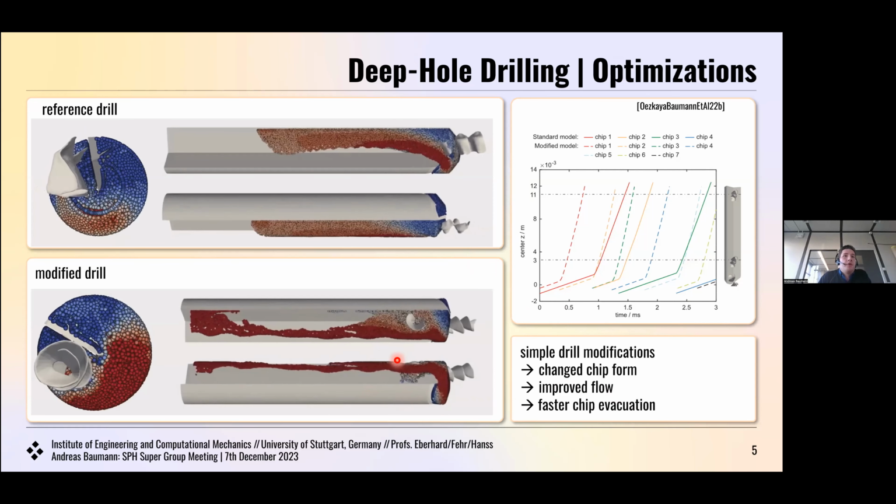It becomes a bit better, but not much. And by adding a quite severe cut about the tool, we get a bit better flow. However, in the end, we are limited in the design based on the machinability of these fluids. So we need to add them posterior to the machining process, and also by the structural strengths of the drill. We cannot remove that much material out here before the drill becomes just too weak and just snaps also.